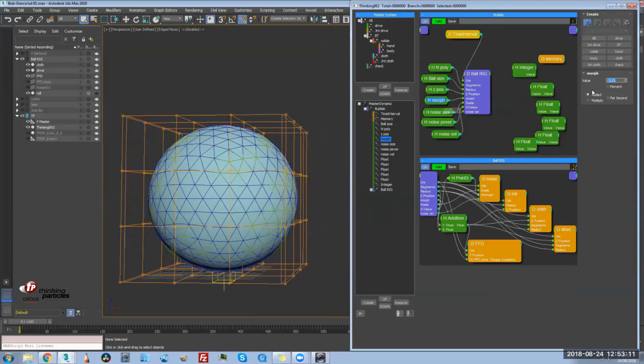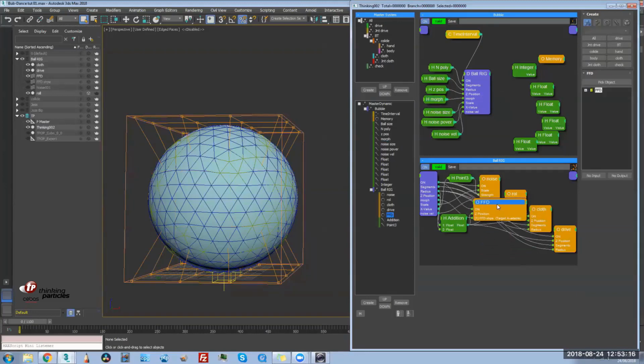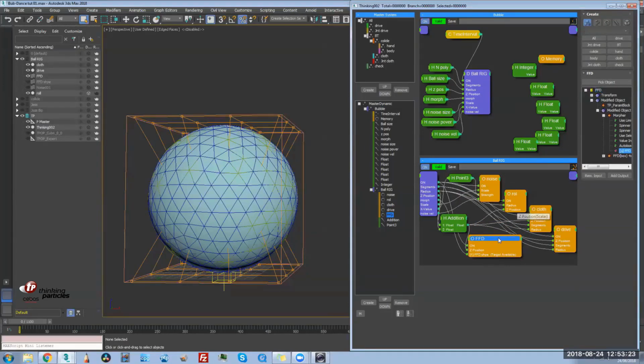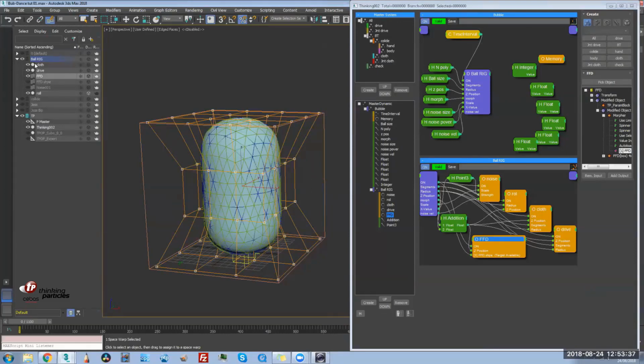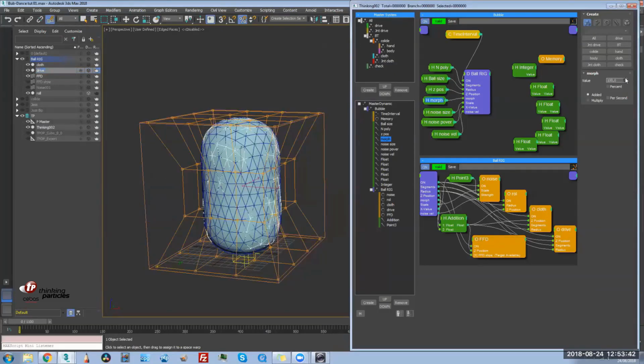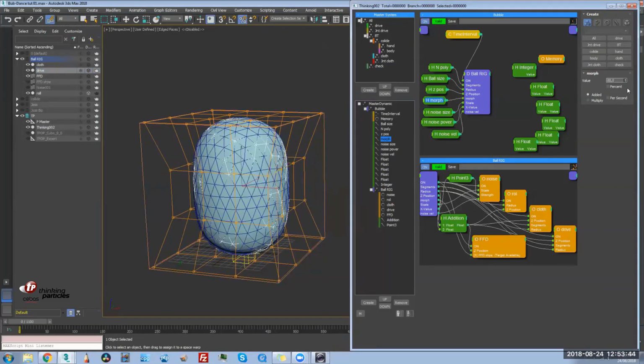Okay, it's not working. Why? FFD, everything is present. It's connected. Maybe it's my mistake. Let's check. Yeah, we didn't assign the space warp to the geometry. So space warp is not like a modifier, and you need to assign it to the geometry that you want to control. So it wasn't assigned. So now it works, as you can see, and yeah, the setup looks ready to go.